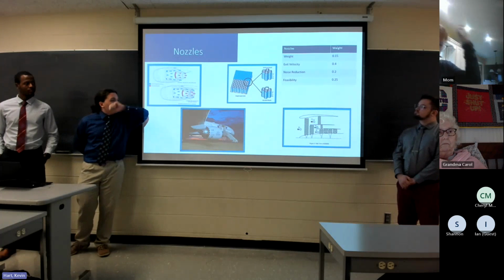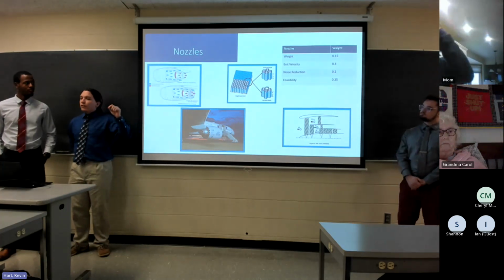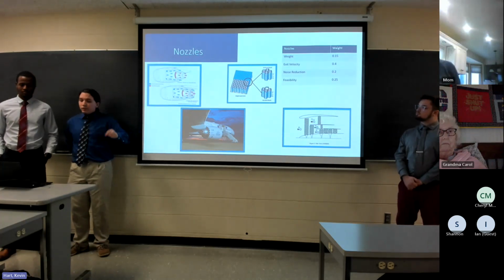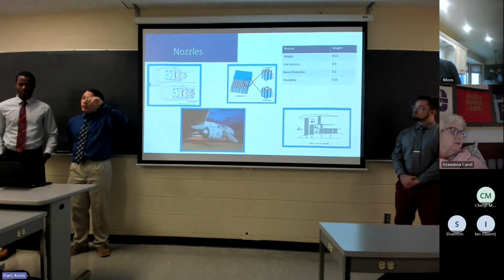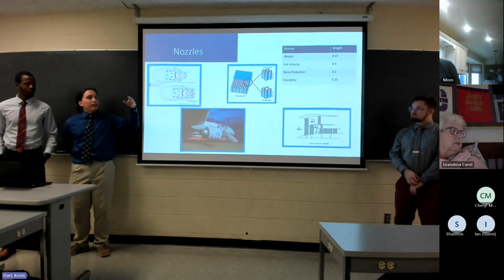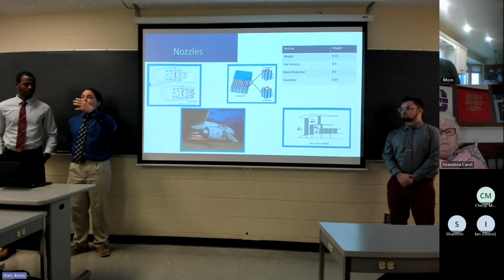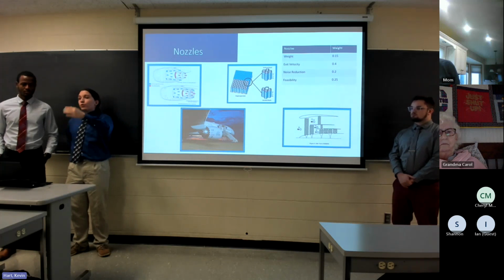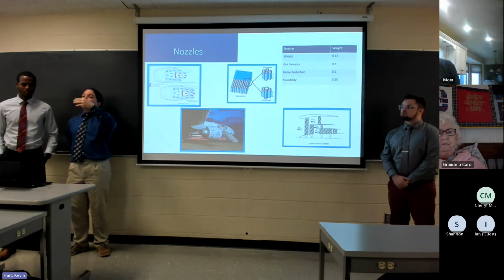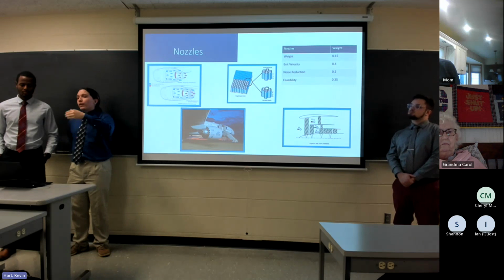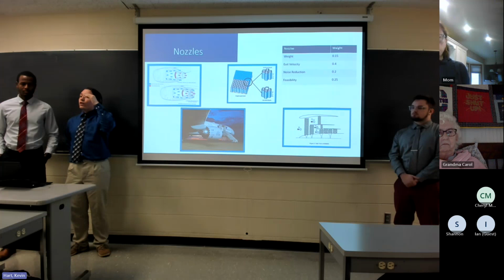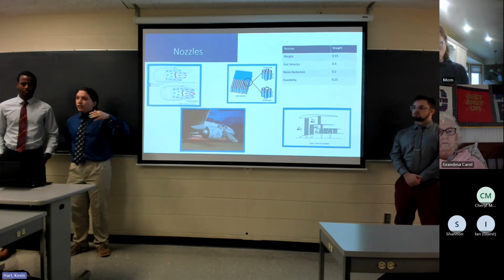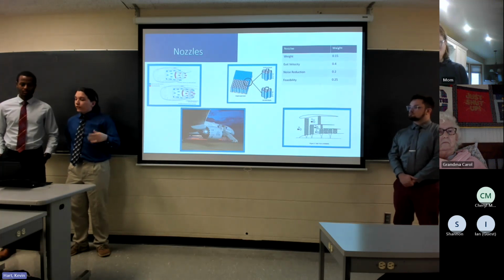Additionally, in the middle, there is a passively controlled nozzle design. This one is essentially a liner on the nozzle, and the premise is similar to when you take a glass bottle and blow over it and it produces noise at a certain frequency. It's the same premise, but in reverse, where as the flow flows over it, it will absorb certain frequencies and reduce the noise production of the exhaust.